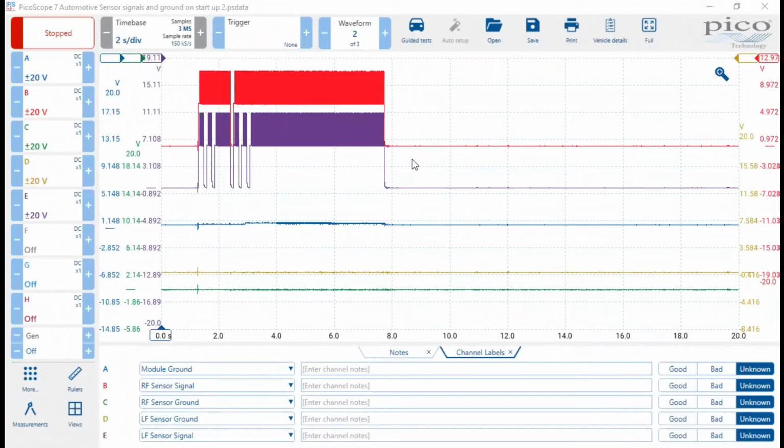All right, so here is my scope shot. Basically, this was taken at the airbag control module, kind of like what you saw on the previous screen. You saw how I hooked it up. I'll explain the wires here. This blue wire is literally the ground for the airbag module, and it looks all right.